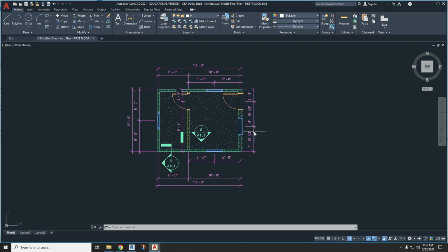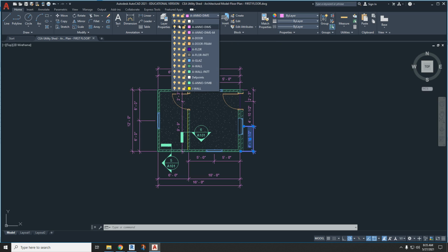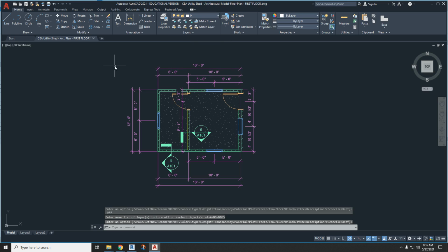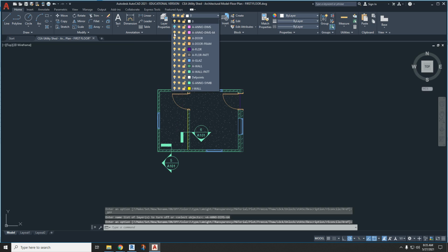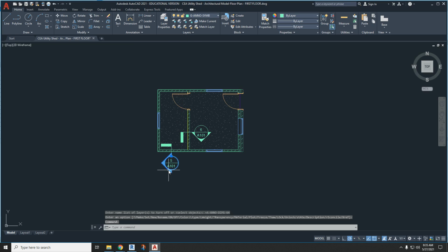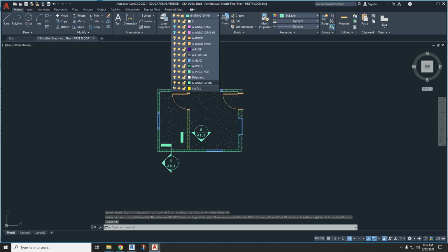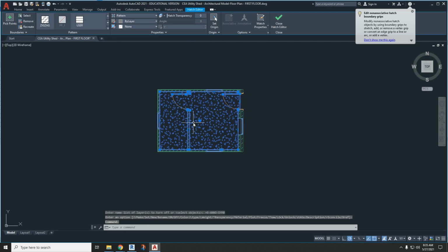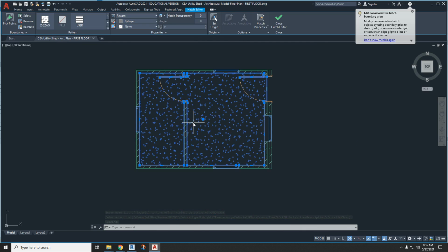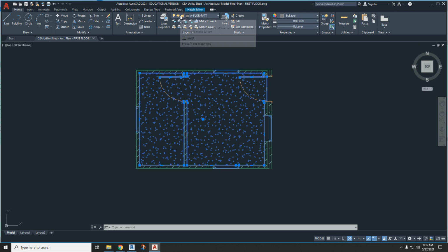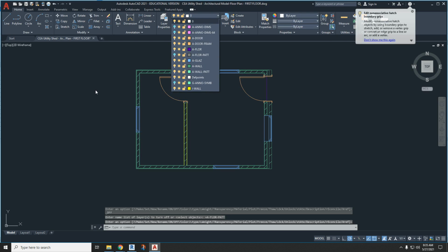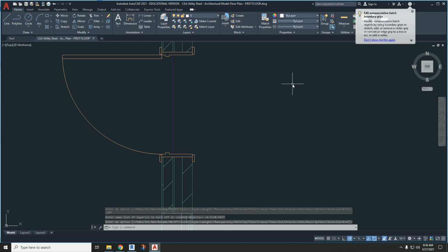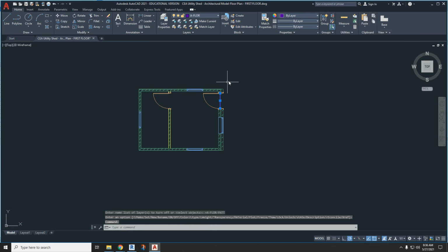All right, so first off, underneath the architectural model, I don't want the dimensions to show. So if you click on that, that's showing up in the A Anno Dims layer. So I'm just going to turn that layer off. All right, and I guess it's this one here. All right, and then also these sections, I don't want that. Anno G Anno Sim, turn that one off. And then I don't want this to show up. So let's see. If I go to home, that's in the A floor pattern, it looks like. Okay, so that looks like, I think, what I want everything else to show up as.